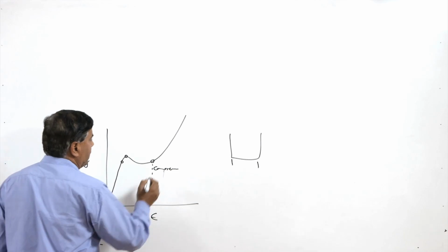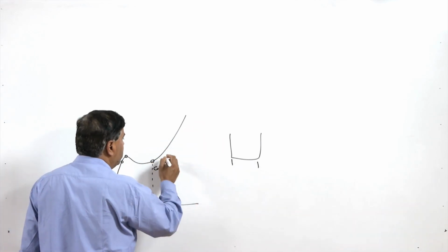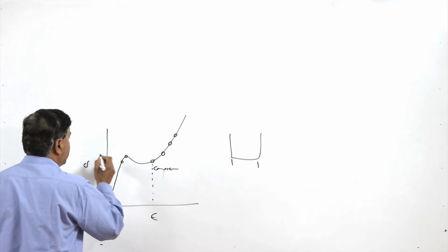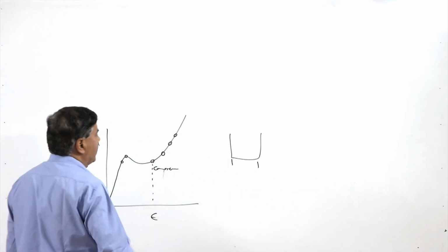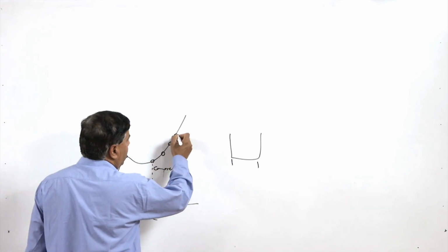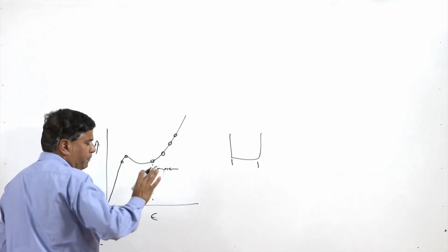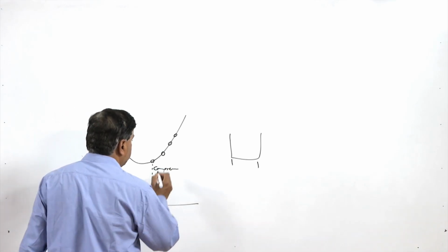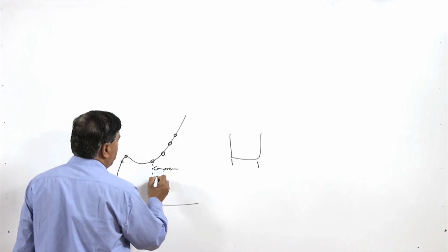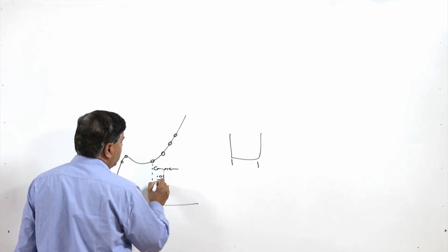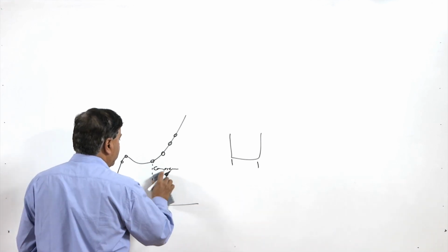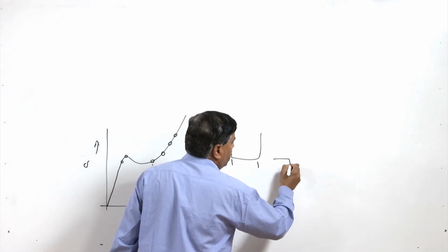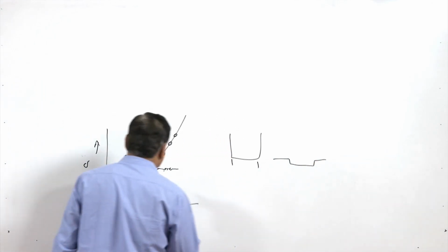As the punch goes deeper and deeper into the sheet metal, this strain will keep on increasing. At the same time, the stresses being induced will also keep on increasing, and a stage will arrive where the crack will start nucleating and its growth will continue. So, schematically, this is for one particular value of the penetration, say the punch is penetrating into the sheet by a certain magnitude.